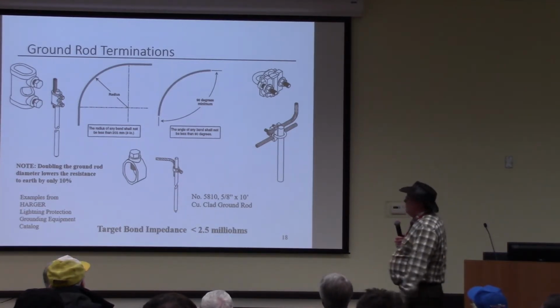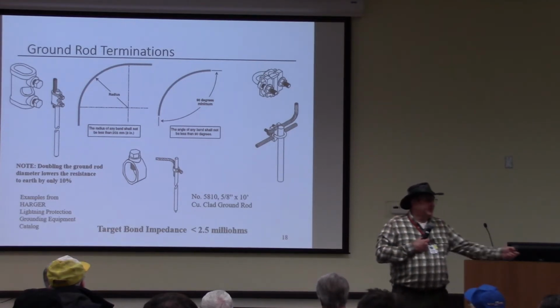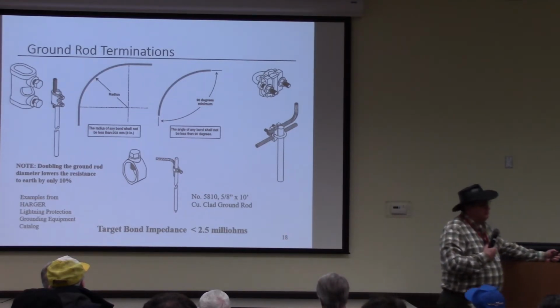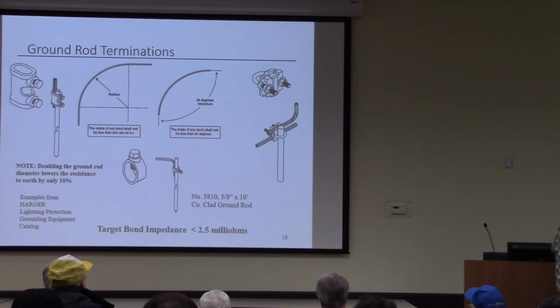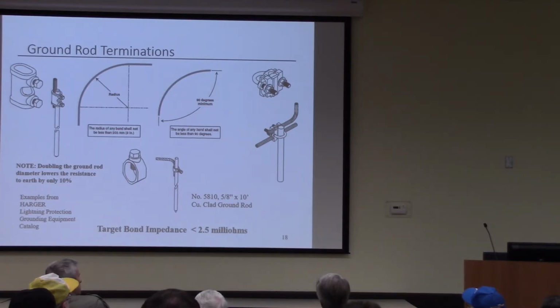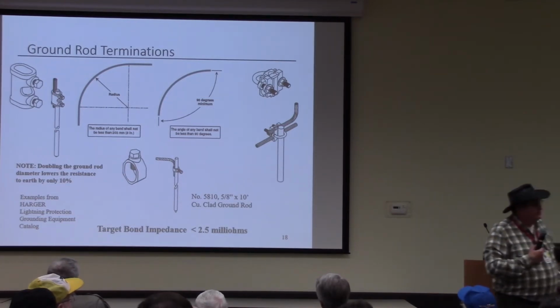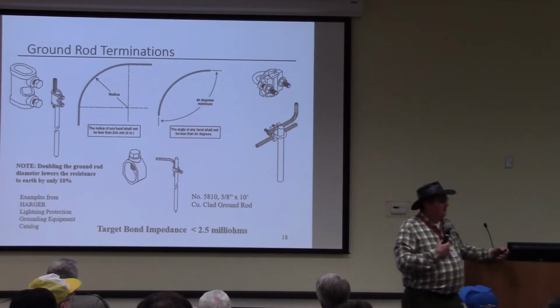Is that for all size conductors? No. As far as the idea of it trying to straighten out, yes. As far as the mechanical strength of it, it depends on how strong you put it in. The fields are generated by the total current going through the wire. You're asking about the current density on the wire. The current density is going to be less in a larger wire, but the field strength should be the same.